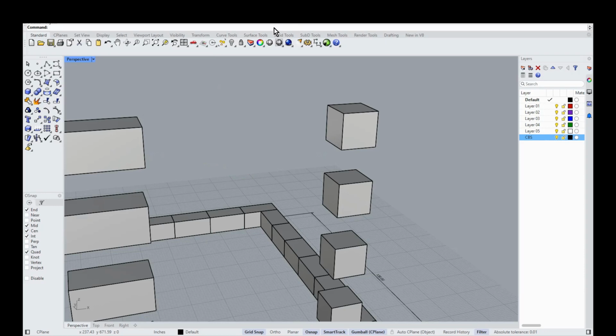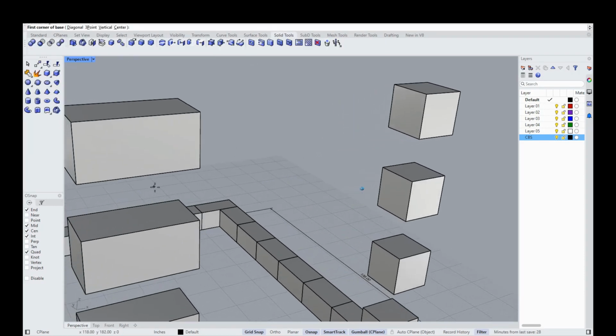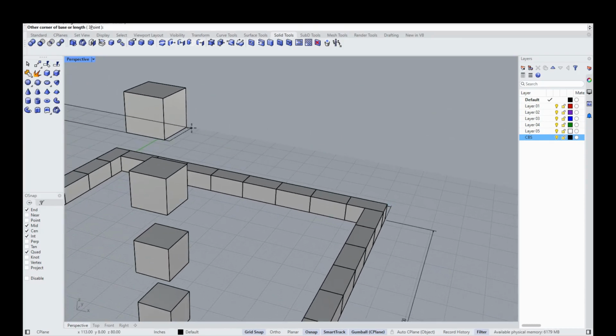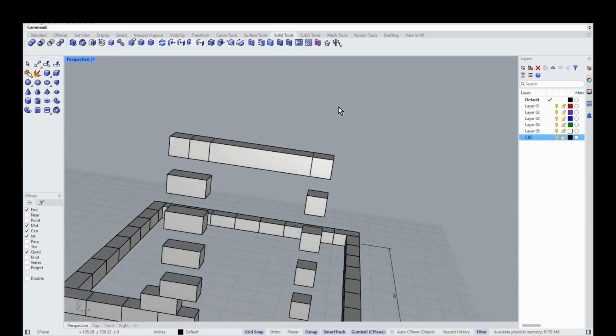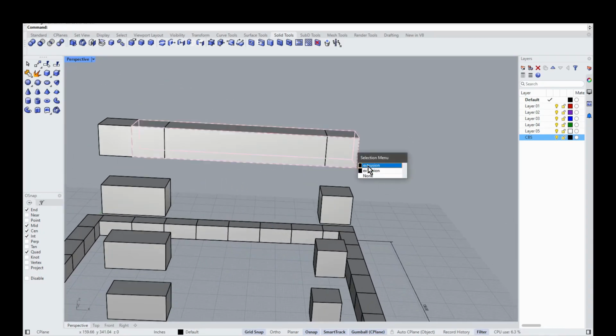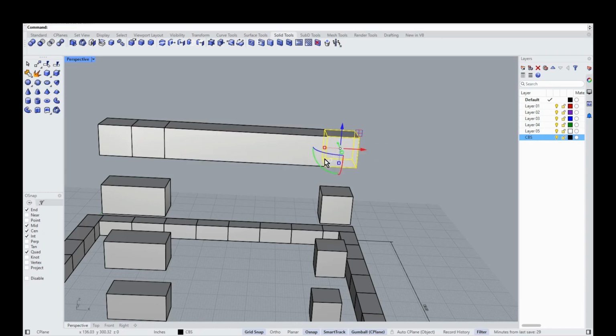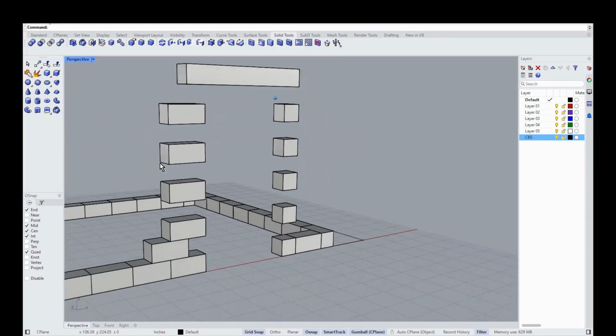That's one way to do it. And then there's another way directly within Solid. This thing basically does the same thing, so it cuts out the sketch. So we go from here to there and up, and bang, you got your lintel. And then you click on it to get rid of the old blocks, and it's going to give you options. So we get rid of that, get rid of that. Now we got our lintel, it's in place.